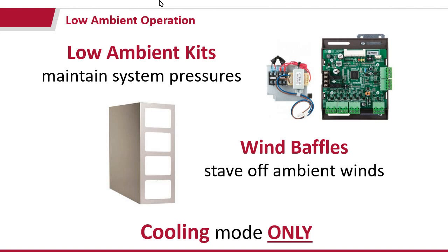Where is it going to find any sort of heat in all that cold air? Nowhere. So you need to maintain high airflows and high levels of air changeover for these units. Therefore, you don't want a low ambient kit that slows your fan speed, and you don't want a wind baffle trapping that air in there and essentially making it a box.